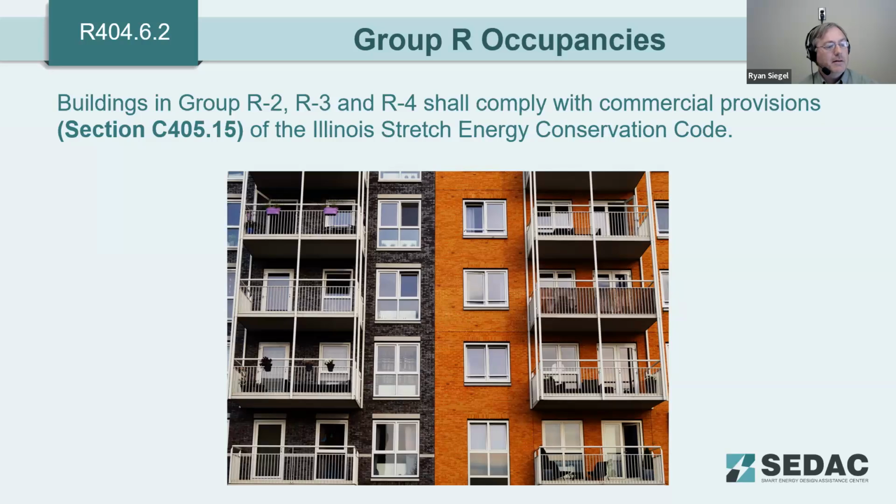Good question about if the future space can be in a sub-panel. I don't think that the code calls out that it has to be in a sub-panel, and I don't remember seeing that either. It does not, I don't see that it prohibits it, but that sub panel would have to be installed as part of the original building installation.